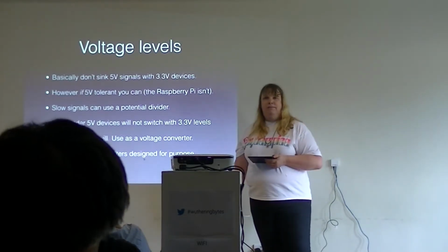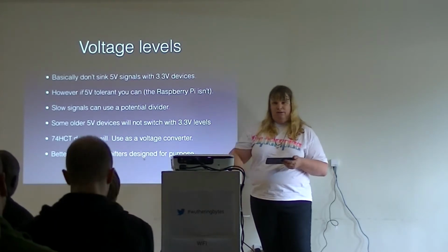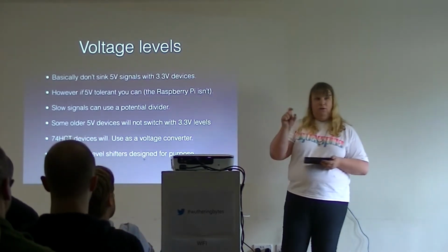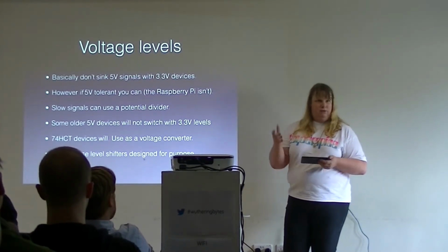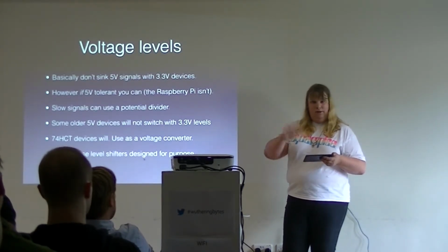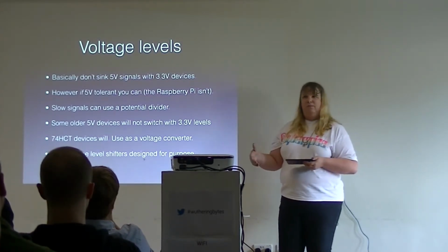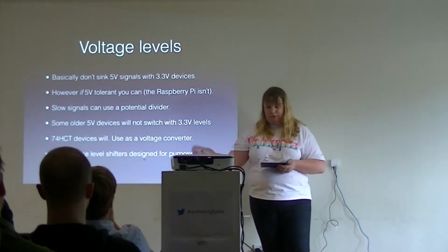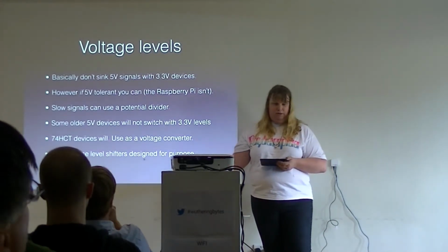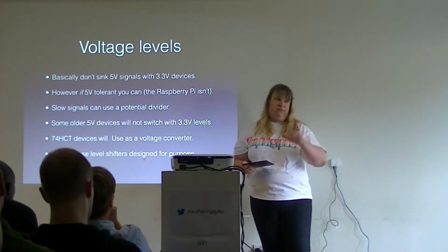However, all the Adafruits and cool components and whatever all have little level shifter boards these days anyway, which will take a bunch of signals and convert between 3.3 and 5 and vice versa. So that's the nicest way of doing it. If you've got a module which is 3.3 volts and you want to use it on a 5 volt Arduino, get one of those, and vice versa.